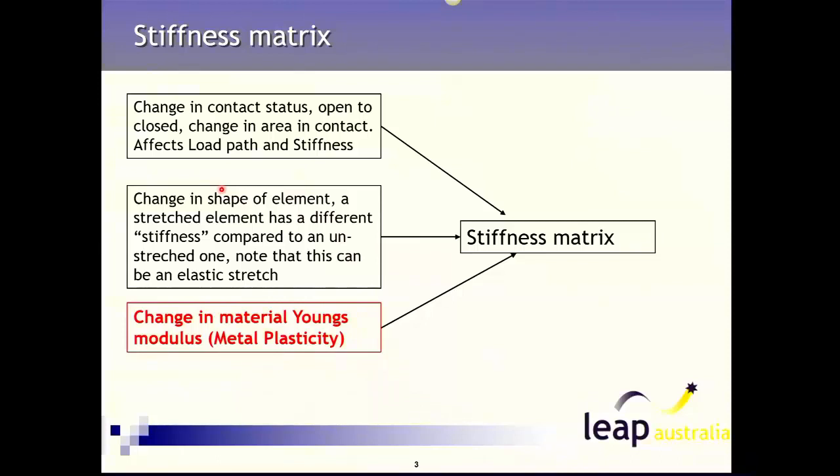If you take a simple structure like a flat sheet, initially that doesn't have any out of plane stiffness. As soon as you apply a load out of plane, the structure will deflect out of plane. And in order to take account of that deformed shape, you need to update your stiffness matrix based on the change in position of the nodes. With a linear model, that isn't taken into account, and that's why we say that for linear models, we assume small deflections. So the deflections don't have an effect on the stiffness matrix.